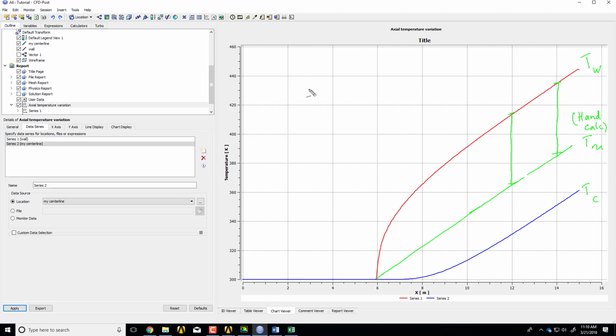And if you look at the definition of the convection coefficient, I want to get the heat transfer at the wall, which is known. So you use h, and then you multiply it by the difference between the wall and the mixed mean. Usually you use h to get that, right? But here, you know this is a boundary condition. So that's constant. And when the flow becomes thermally fully developed, that's constant. So that's constant, and we can calculate that. And then if you non-dimensionalize it, you'll get the Nusselt number. So you can see why the Nusselt number has to be constant right over there.